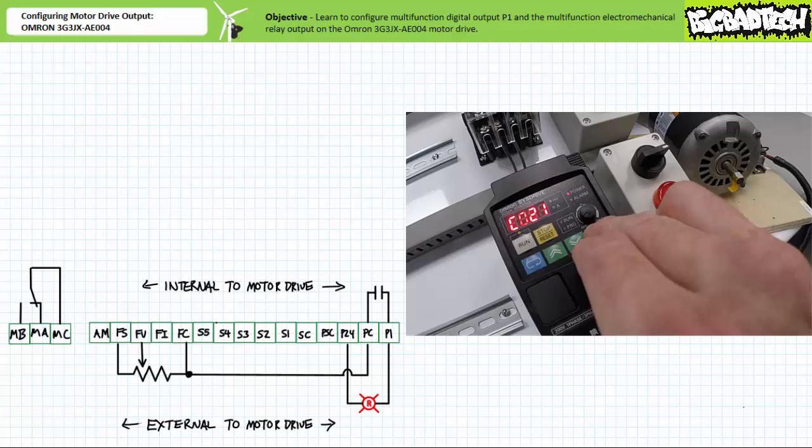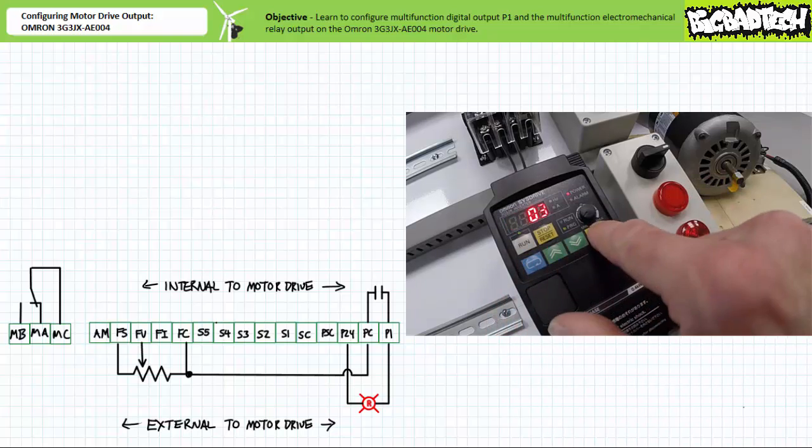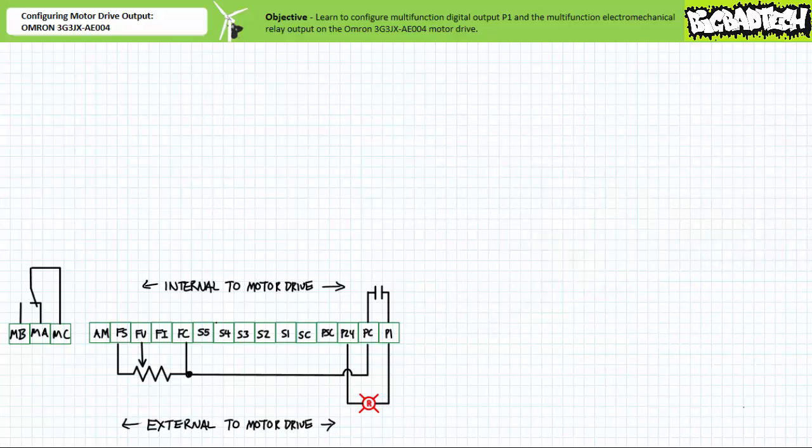Navigate back to communication parameter C021, multifunction output terminal P1 selection. Increment to 03, or the overload warning function. This setting signals when current draws in excess of the adjustable communication parameter C041, overload warning level, currently set at 1.1 amps. If you're tracking, you should be able to predict the behavior of this pilot lamp in 03 overload warning mode during acceleration, constant speed, and deceleration.